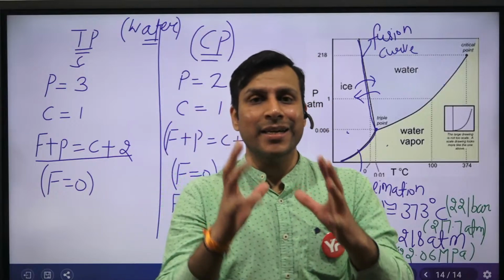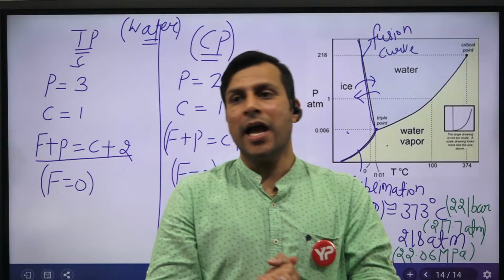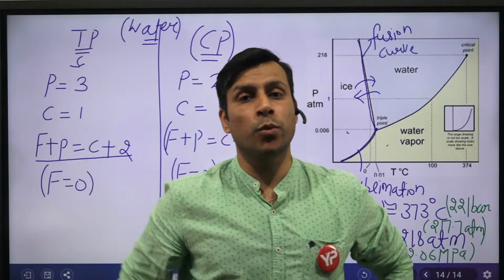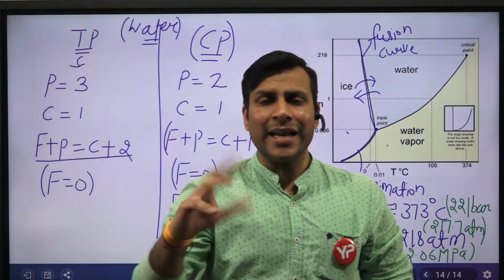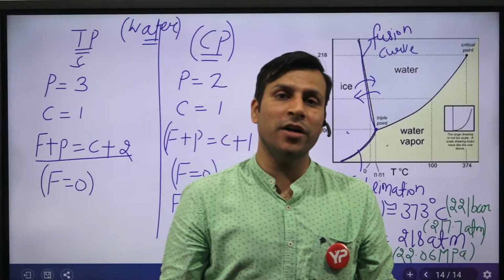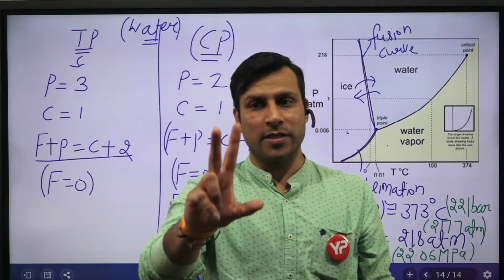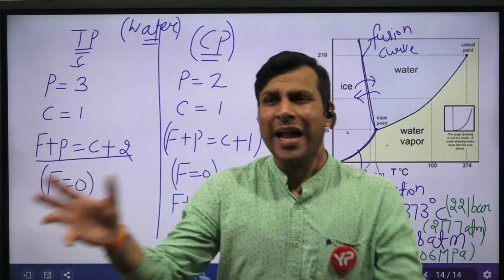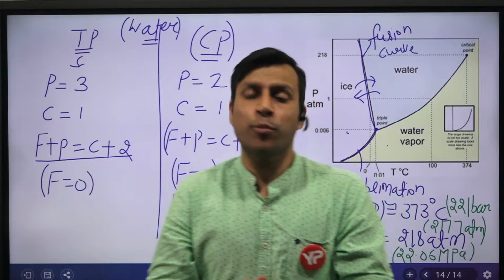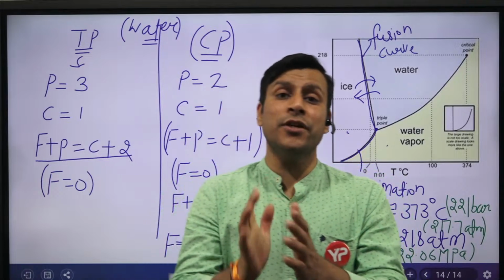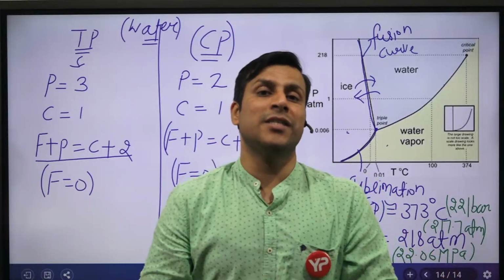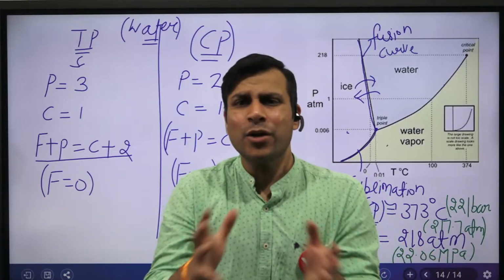So what you can say, at critical point there are two phases. Okay, and at critical point directly that particular liquid is converting into steam. Okay, and actually this is a more effective way, guys. Just remember this. If anybody will ask you what is a critical point, so what you will say, sir, at critical point there are two phases, like critical vapor and critical liquid, and both are having almost same density. Okay, so this is that particular point for a particular substance at which the liquid and vapor both will have equal density. Okay, so they are not actually separable, they are not distinguished.